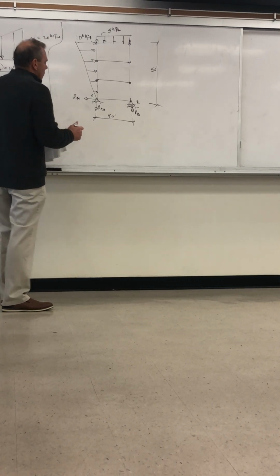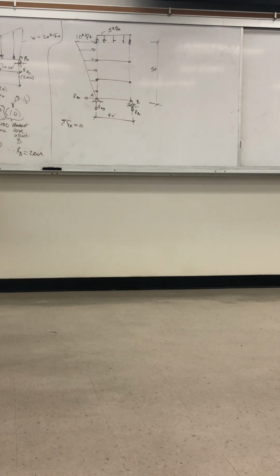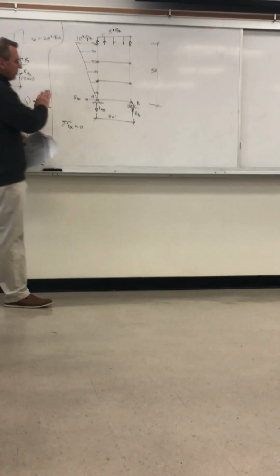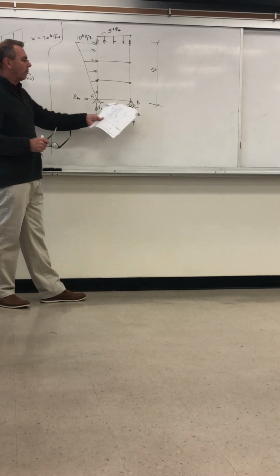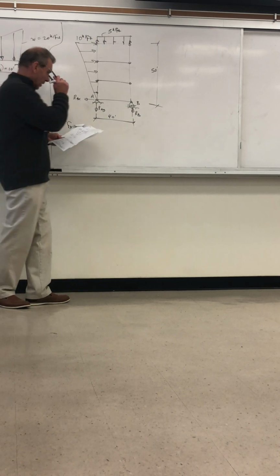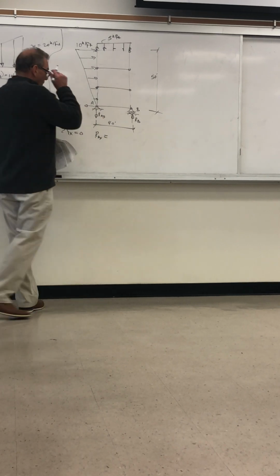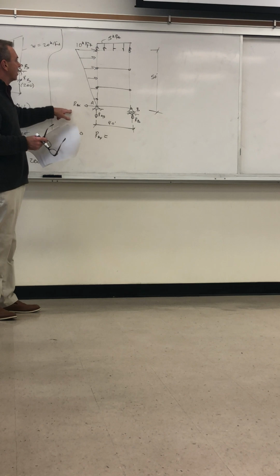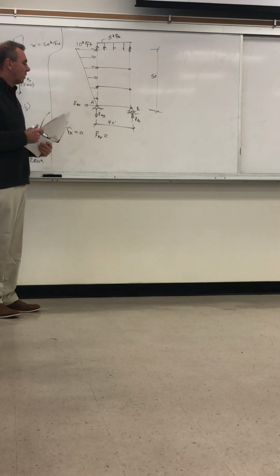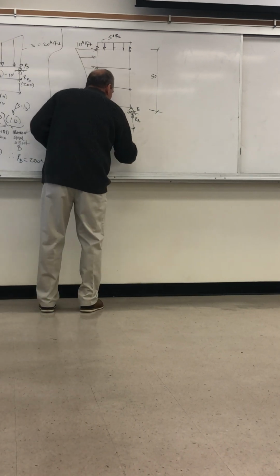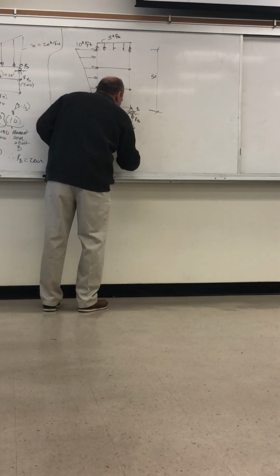So first, let's do a summation of forces in the X is 0. And in this case, it's not going to be trivial. We actually have a value because you have this large lateral force that wants to push the building and roll it to the right, and it's being prevented by this reaction, not by the roller B. It's not taking anything, right? So we get reaction AX is, and now we're summing forces, so this is a force to the left, the reaction, with no movement, and then the force to the right is this whole area, right? So it's just 10 kips per foot, so it's 10. It's a triangular area, so it's 10 times the height of 50 divided by 2.